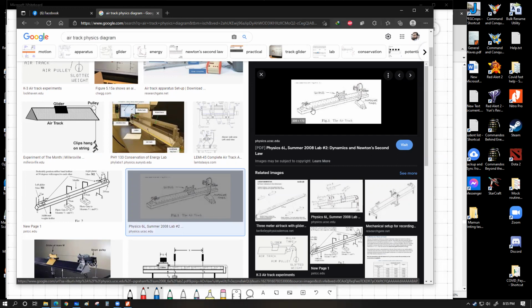So this whole triangular structure basically is a hollow cylinder. One end is totally closed. The other end is connected with a pump that pushes air into this chamber, and that air is given out through these tiny holes at a low pressure. At a slightly higher pressure than the atmospheric pressure. That's why I'm using the term low pressure. I mean, the pressure difference is not so high. It just doesn't make a very sharp flow.